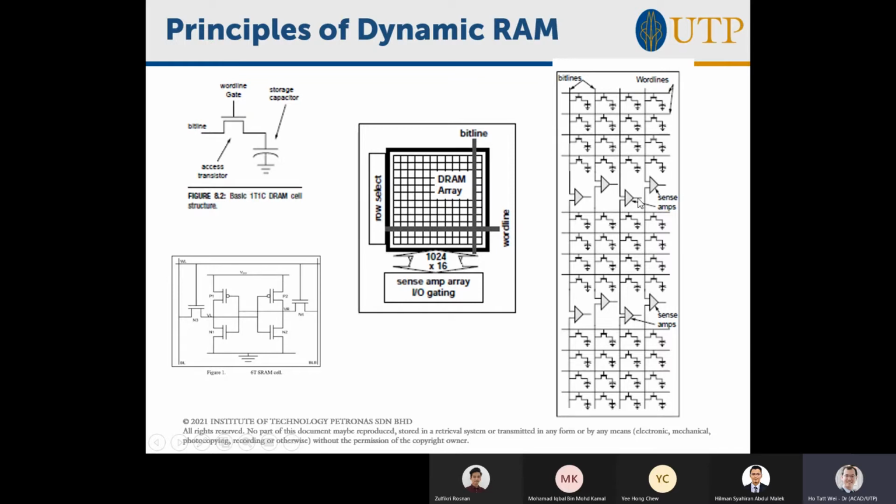And all of these, 1, 2, 3, 4, 5, 6, 7, 8, will go into another level of multiplexer here, and then you will choose which of these, okay? So your DRAM is accessed by having a row select, which is the word line. I'm choosing which row. And you have another column select, which is choosing which of these outputs I'm going to ultimately send out to my 1-bit output. You got that? So what I'm showing you is a dynamic RAM array can only send 1 bit, because it's storing 1 bit. Even the static RAM is storing only 1 bit. It's just got true and the complement of it.